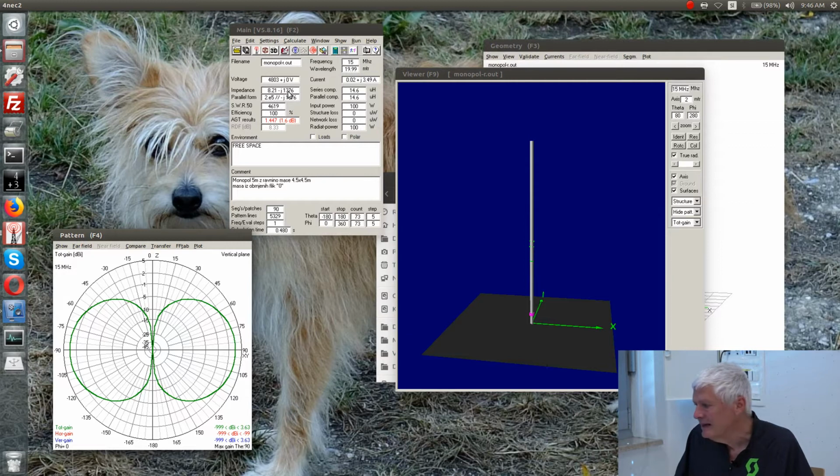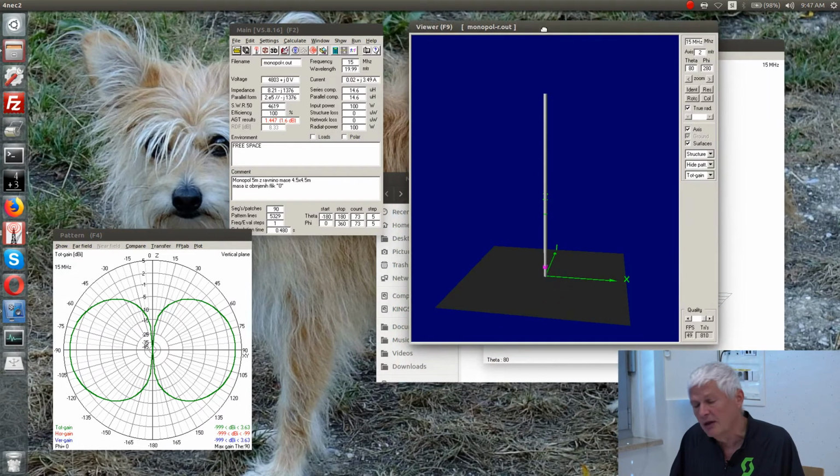Why? Here we have patches that are not allowed to flow any currents. So here we actually have an open circuit. And an open circuit has a capacitance somewhere to the free space, and that's a very low capacitance. This low capacitance causes minus j 1000 ohms of reactive impedance. So you see that something is badly wrong here. But unfortunately, people are publishing these things on the web without thinking much. So this is really a problem.